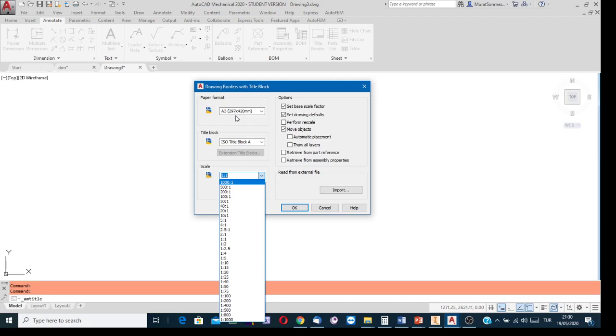But the object is a civil engineering architectural object. It is a house. The width of the house is 10 meters, 10,000 millimeters. So if it is so, then select a diminishing factor for fitting the views of such a big object. For instance, select 1 to 40 as the diminishing factor.